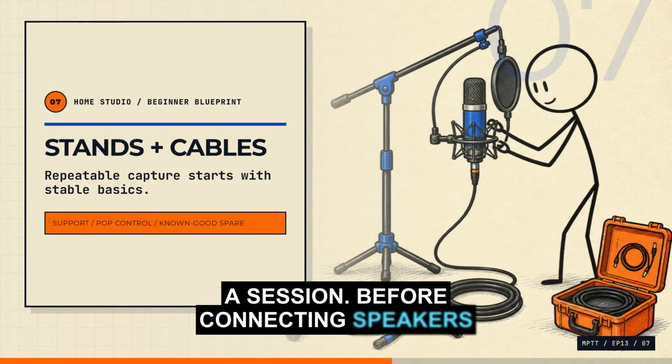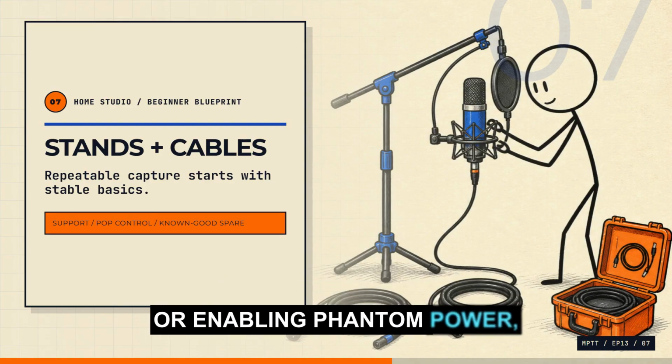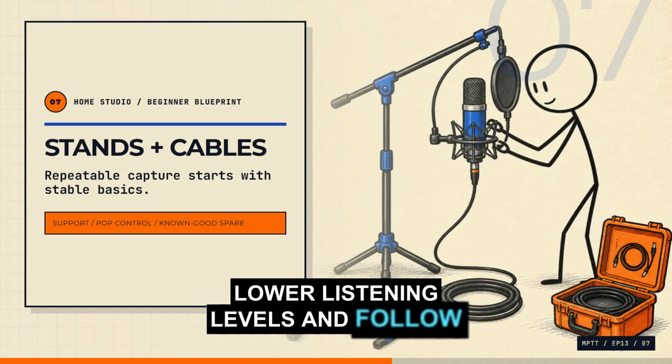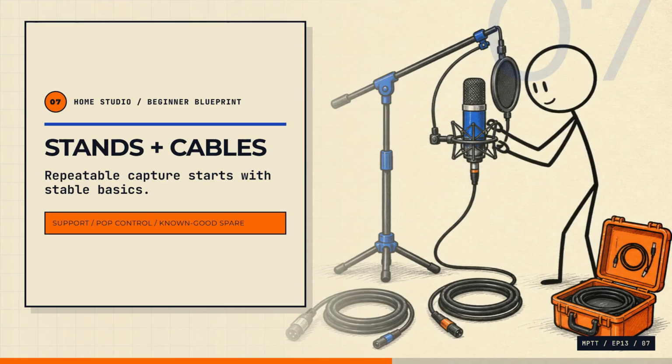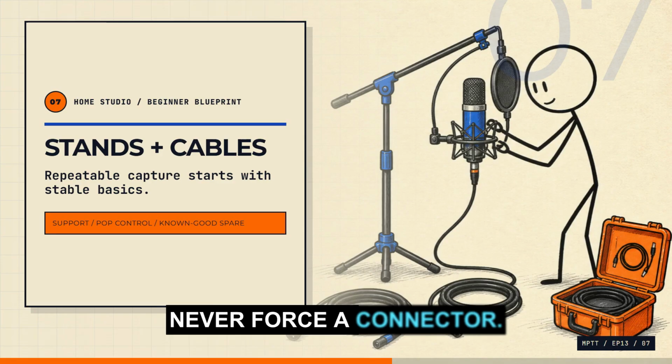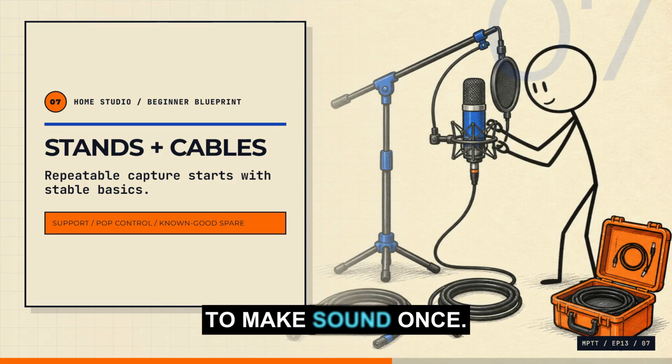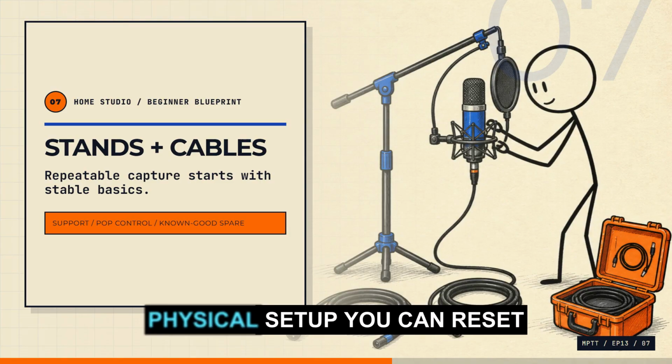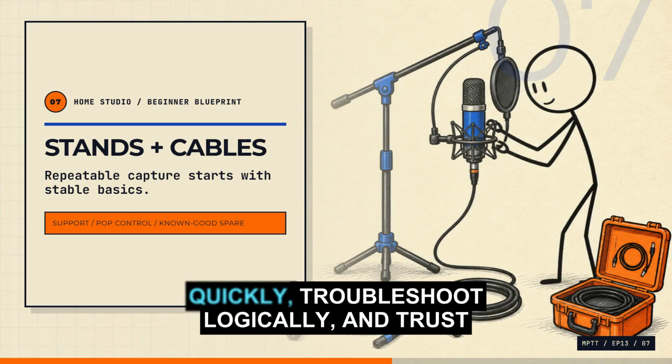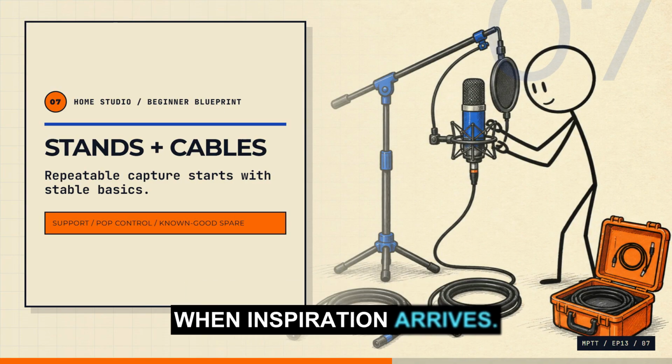Before connecting speakers or enabling phantom power, lower listening levels and follow the hardware manuals. Never force a connector. The goal is not merely to make sound once, it is to build a physical setup you can reset quickly, troubleshoot logically, and trust when inspiration arrives.